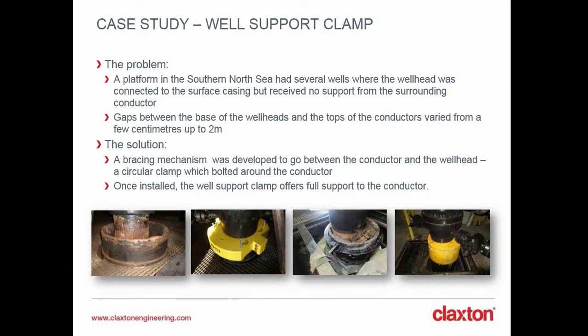Once the clamps were fitted, and you can see them fitted in pictures 2 and 4, the wellhead load would then be transferred to the conductors, which is why it was also important to verify the integrity of the guide as well as the conductor. The repair options are based on previous experience or industry knowledge, but the effectiveness of each option is governed by factors such as, as I mentioned before, the integrity of the conductor and the integrity of the guide as well. So it's important those 2 aspects are also checked.